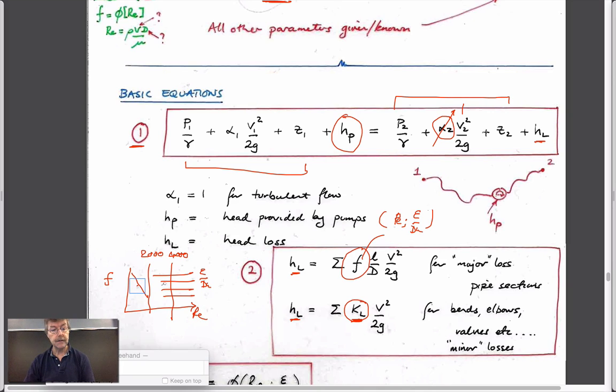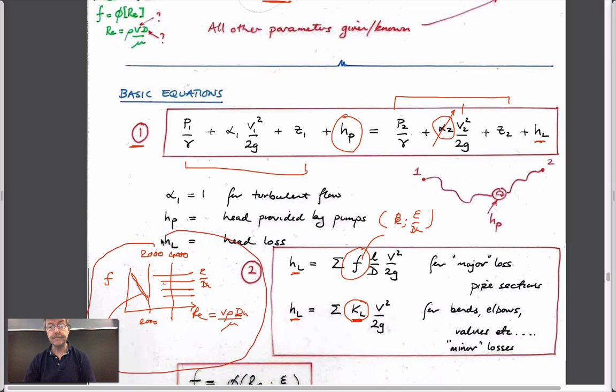But at low velocities or low Reynolds numbers, less than 2,000, and we know that Reynolds number for this use is always defined as a function of characteristic length, a diameter or an equivalent hydraulic diameter, for laminar flow it's some function of a constant divided by Reynolds number. And so we've spent some time talking about this. So this is what feeds into this. Okay, so that's the 5-second recap for the morning.